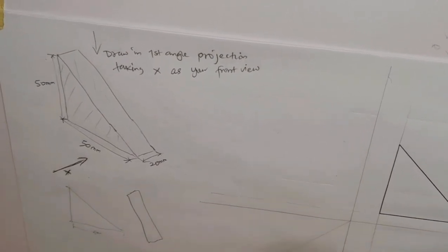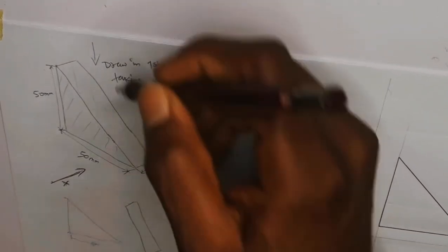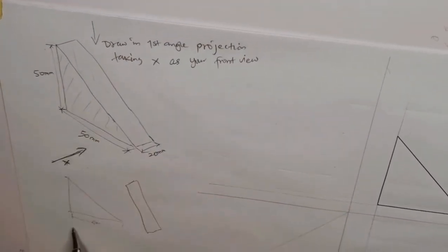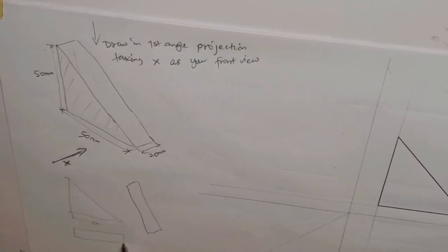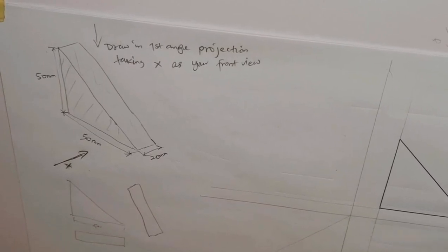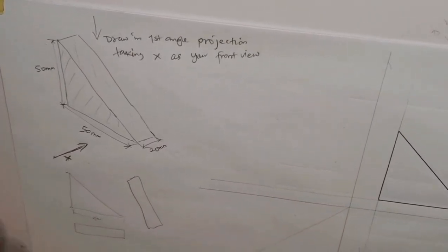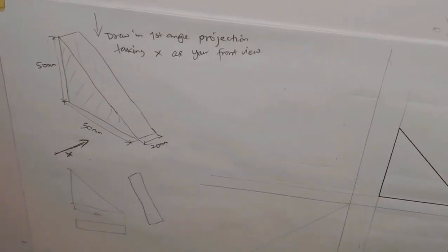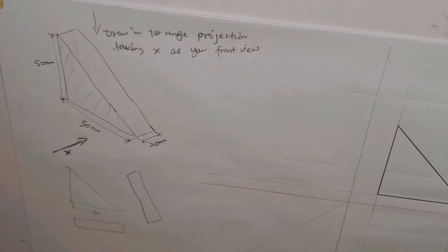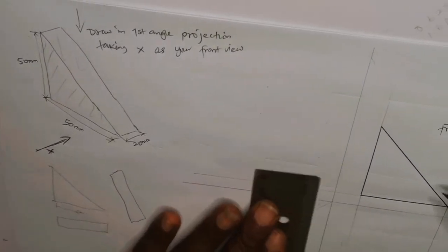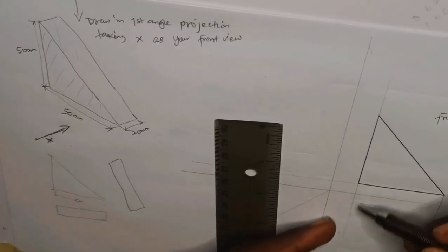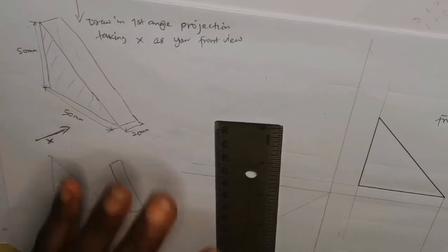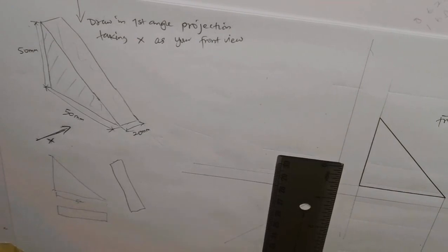Like maybe a rectangle, it becomes flat. So if I look at it in this direction, which is on top, it will look something like this, flat. So please take note so that you won't make such a mistake. I'm seeing this section here to be flat, and the dimension is 20 millimeter. That's why I suggest we draw the projection line. You can see the projection line is telling us that it will be flat. Understand? It won't be slanted.